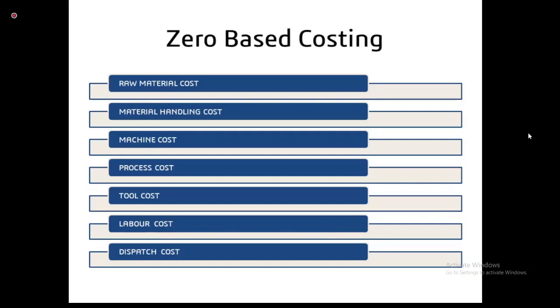Secondly, whenever you are doing costing, you have to consider how many manufacturing approaches are going to be carried out on the component, because that decides the machining time and the aspects of machining involved in the product. For example, if I am going to machine a component, first of all I need to understand which manufacturing processes are involved, like whether there is rough milling, contour milling, finish milling, or a drilling operation.